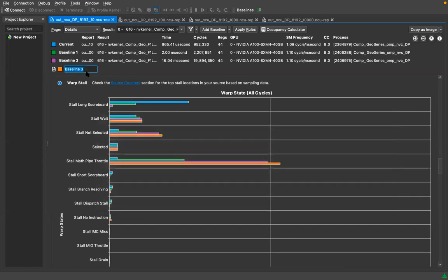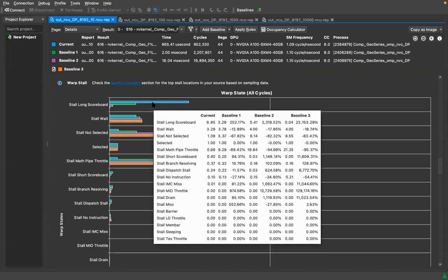So in this case, we have less operation, less FMA instruction per data transfer. We have a higher stall cycle here, right? And compared to the orange one, the orange one has very localized repeated computation happening, so the stall ratio is very low. But in this case, the stall ratio is relatively high because of the data transfer. The kernel is waiting for the data transfer completion, right?